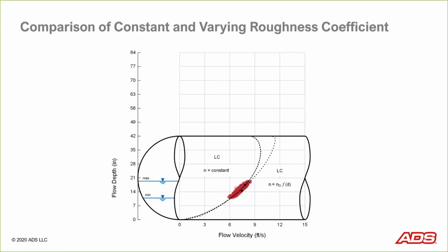But one of the wastewater professionals of a past era, Thomas Camp in the 1940s, did a little research on this, and he concluded that the roughness coefficient does vary a bit as a function of flow depth. And he came up with a relationship for that. It's often described as Camp's varying roughness curve. There are some equations to approximate that, and there's some other researchers that have put out some information on that.